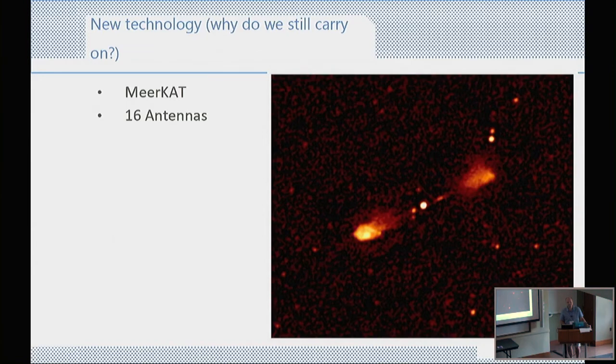Commercially available ASICs, spectrometer ASICs, and the FPGAs together? Not really, no. In the future, that's going to be a strong contender. There's a Swedish company, Omnisys, that has an ASIC spectrometer, and also Pacific Microchip, which has evaluated their new spectrometer. And I could see how the FPGA and the spectrometer could work in sync, where you can move a lot of the heavy processing that's so power hungry into the ASIC, because you're always doing a poly-phase filtering.